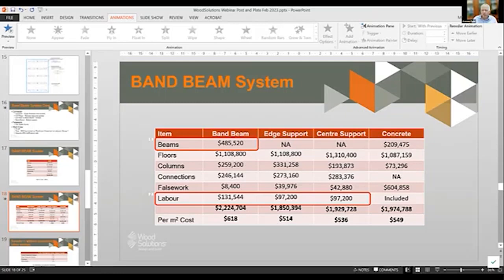systems. So it's interesting to see that these post and plate systems are not labour sensitive, and even though we did our utmost and put inefficiency rates in that, it wasn't a criterion. It really is a material cost. The labour was about 5% of the overall superstructure cost. I facetiously said to people that you may be able to negotiate that 5% labour cost out of material supply, but I'll leave that to others.